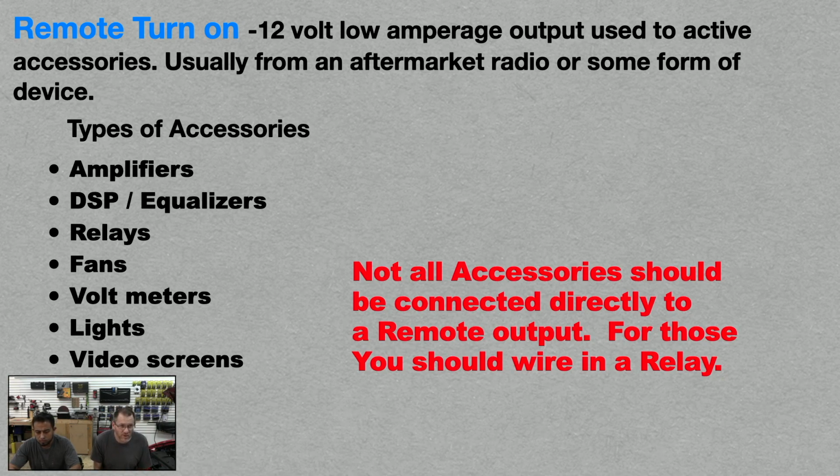Some of the things you might turn on: amplifiers, DSP EQs, relays, fans, voltmeters, lights, video screens. Not all accessories should be connected directly to a remote turn on output. For those, you wire in a relay.